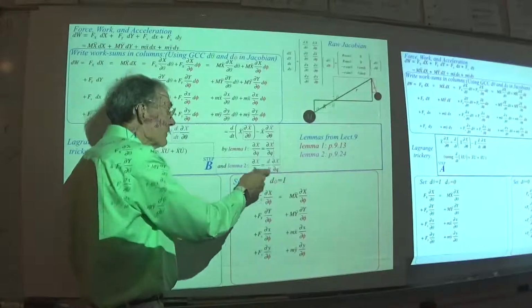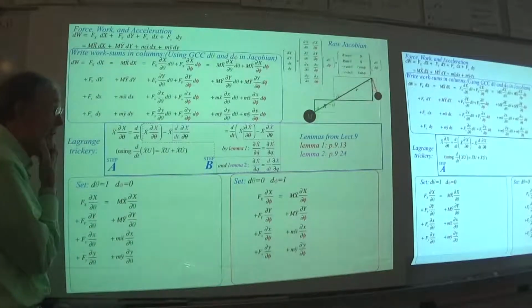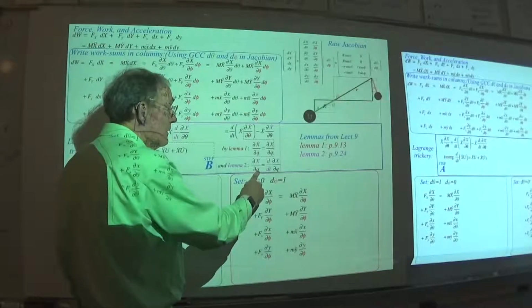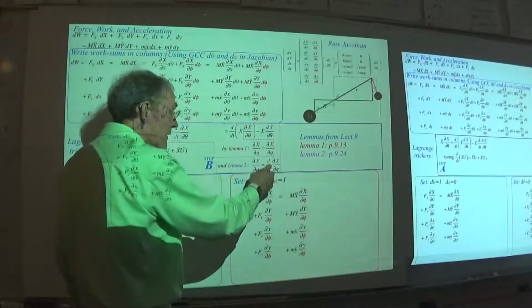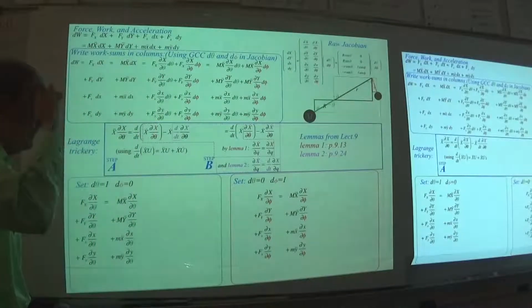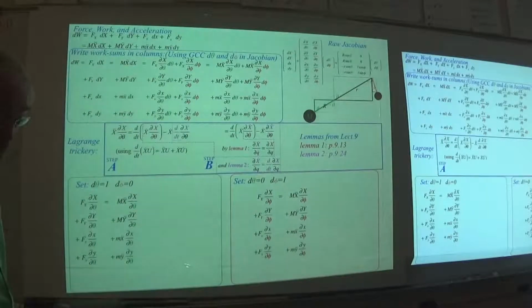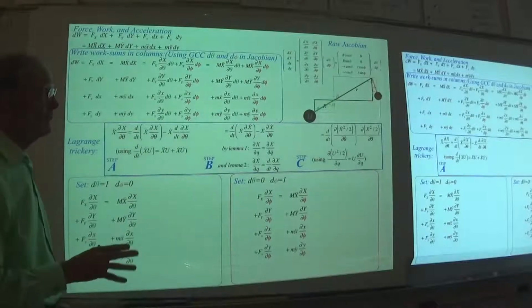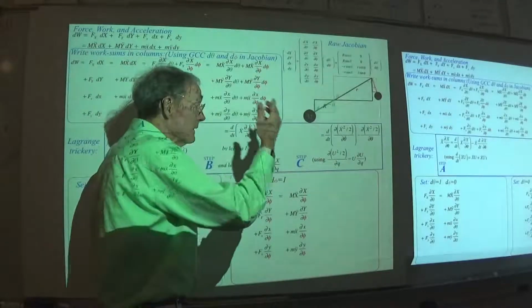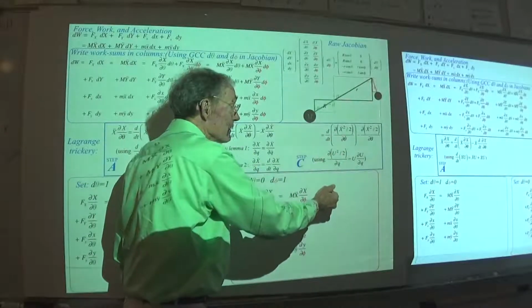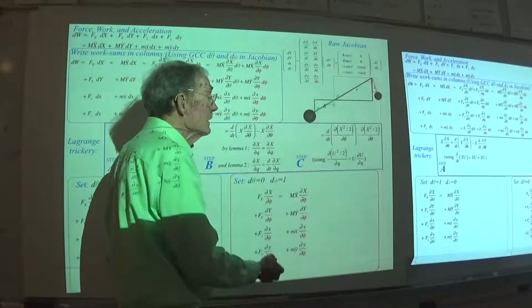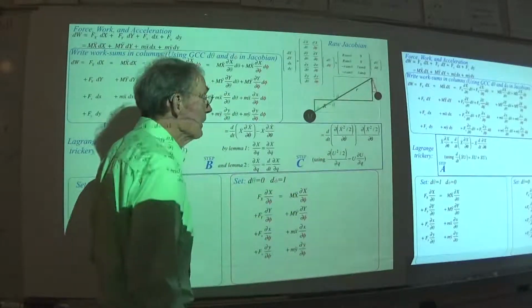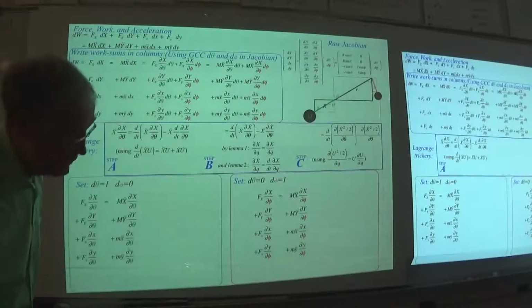This was a little trickier because acceleration requires some extra thought. But this basically says that the partial derivative of x dot with respect to q is the total derivative of that Jacobian component, x with respect to q. Okay? So basically we replace, using this, the stuff that we're talking about. And then the final step is to realize that's how we get a combination that involves just the kinetic energy. This is true for all of the variables that we're working with right here. So this is just the final step in the Lagrangian derivation.